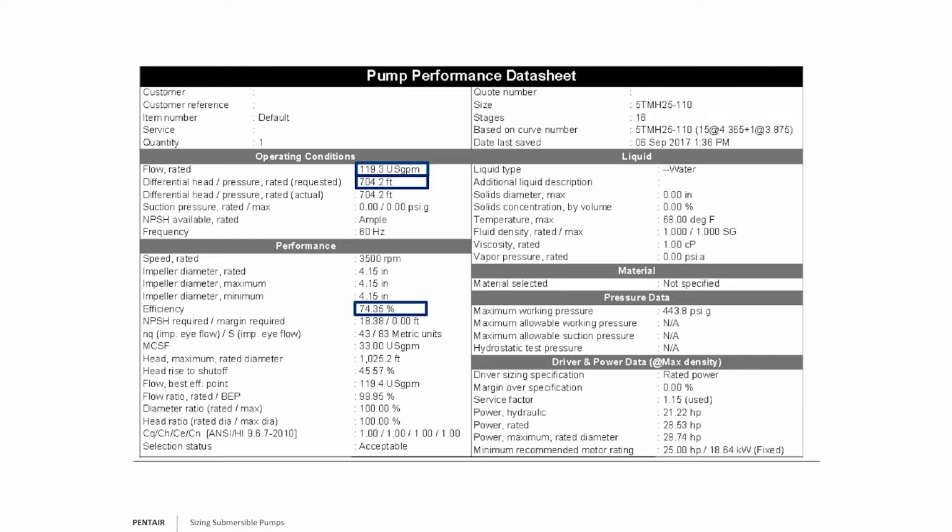Now, at the efficiency point, I said about 75. Let's say 74.35. That's pretty accurate. It was a pretty good guess. The reality is, it's a memory game for me. As I'm sure you know, I probably give this lecture multiple times, so I can't remember every number. There's our 18.38 of net positive suction head required. That's where I got that number in that earlier example that we did the math with. So here you find your exact number.